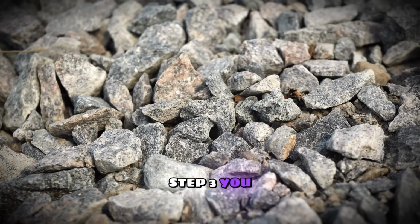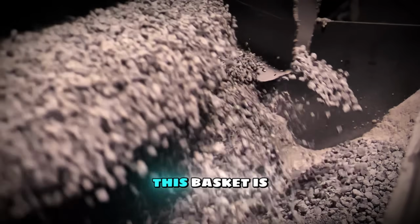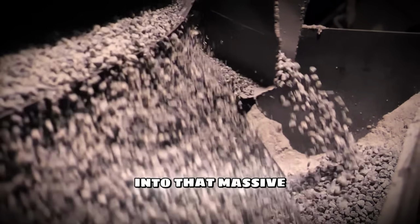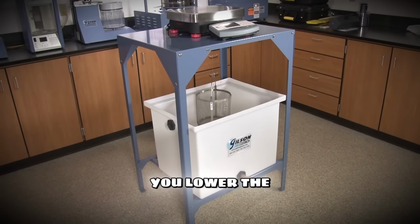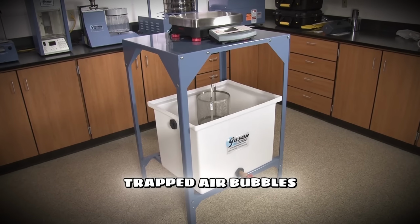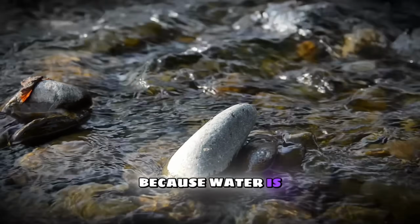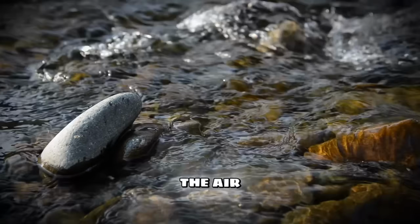Step 3. You place those rocks into a specialized wire mesh basket. This basket is suspended directly from a precision scale that sits on top of the bench, hanging straight down into that massive 30-gallon tank of water. Step 4. You lower the basket fully into the water, give it a shake to release any trapped air bubbles between the rocks, and you read the scale. This gives you the weight in water. Because water is pushing up against the rocks, they will weigh less underwater than they do in the air.